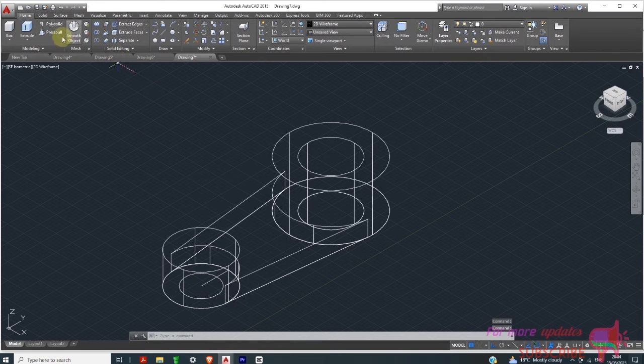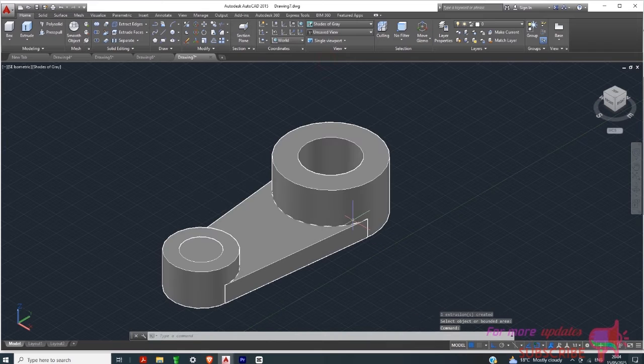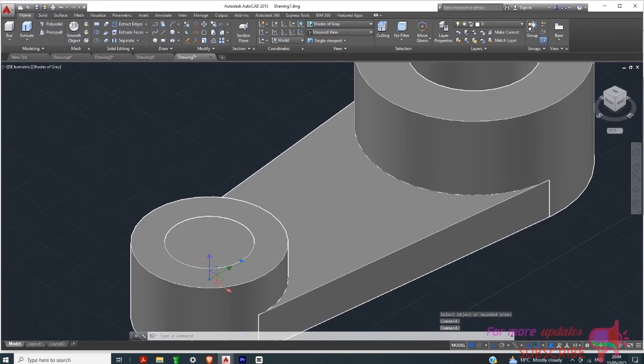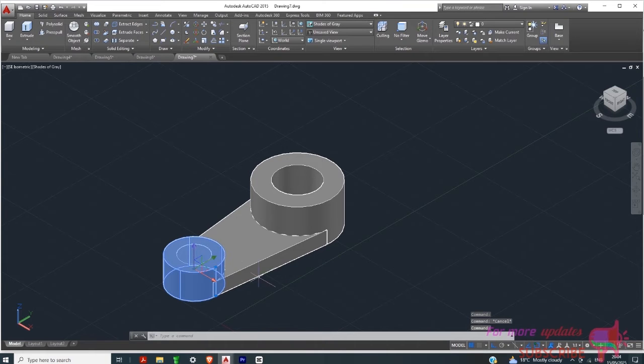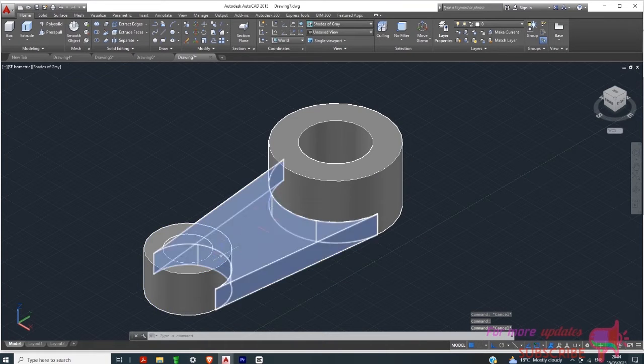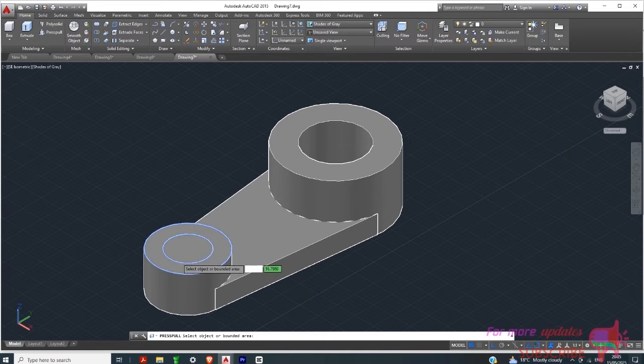Again, I will pick, because this one we did not do it accurately, I need that follow at that point, so I'll just press pull 24, enter. Now I want to pick this part, or just again use press pull, and then 24, enter.